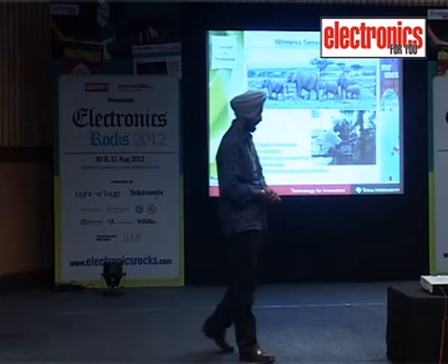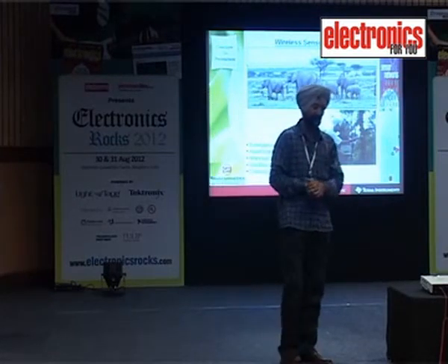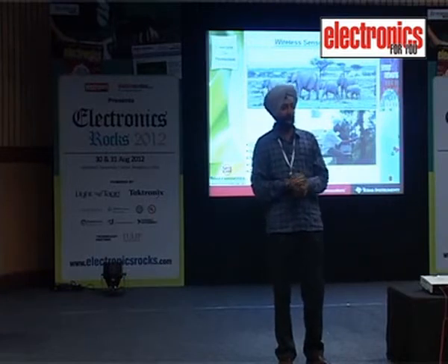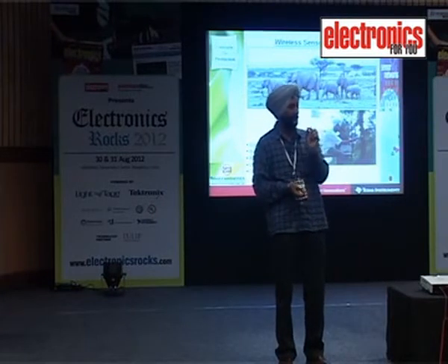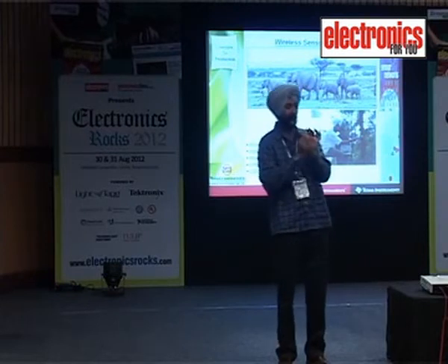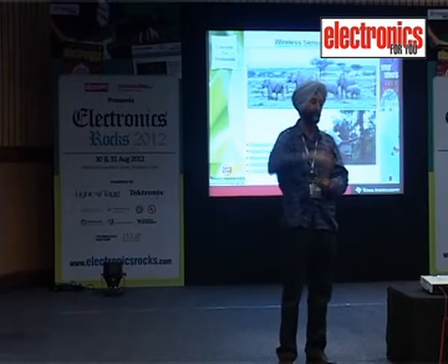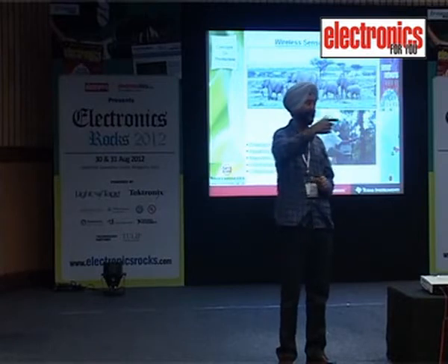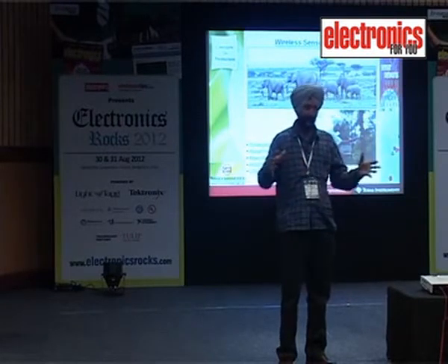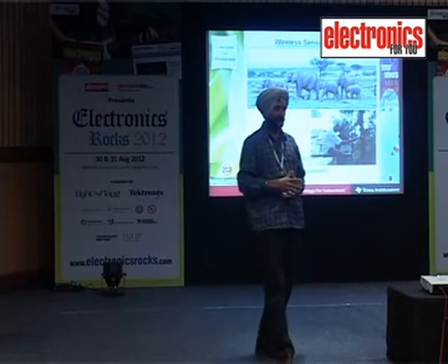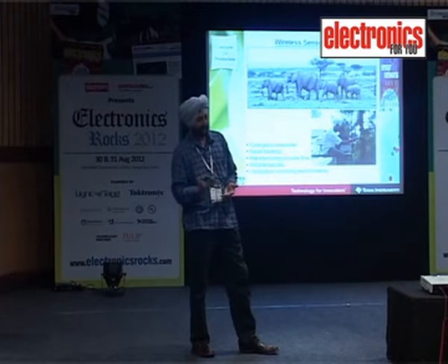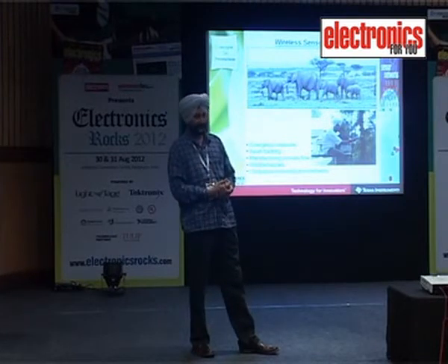Now we are talking about MSP430-based sensors, where the wireless transmission power will be very, very low. The small tree, the small fellow with a small sensor, cannot shout, "Hey, save me." This message cannot go up to 10 kilometers. Definitely, the message will go with a multiple-hopping mechanism through a sensor network. That can be solved with the help of Zigbee, or you can have proprietary protocols, right?